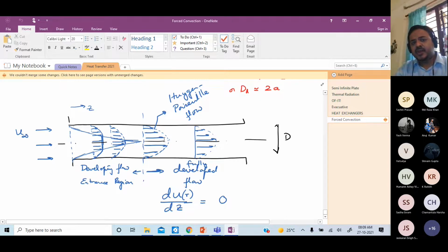After that, the flow profile will remain in this parabolic or paraboloid form, and what is the slope of the parabola, etc., will be all determined largely by the diameter. The flow profile, therefore, under what we call the fully developed flow, is determined by the diameter of the pipe.